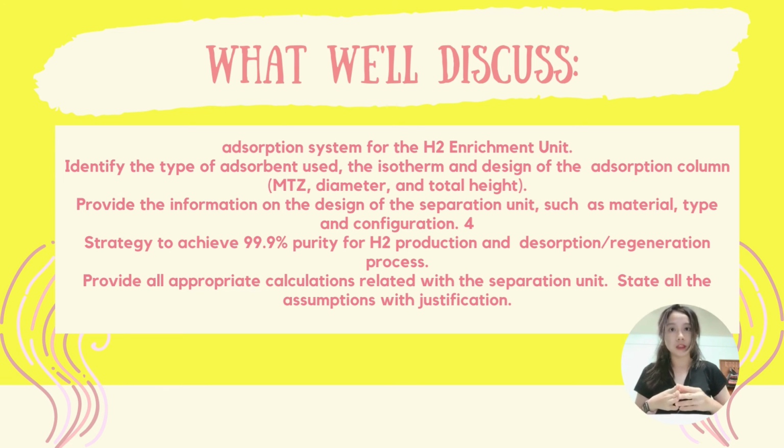According to our research, PSA was the first developed technology based on the Skarstrom cycle that required two fixed adsorption beds to preferentially adsorb one component from the bulk mixture. Furthermore, the PSA system is an ideal separation method due to its ease of application over a relatively large range of temperature and pressure settings.